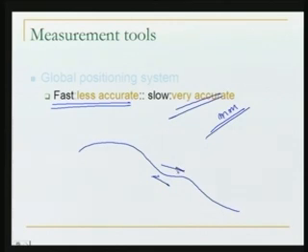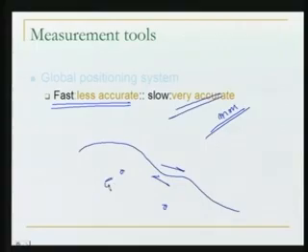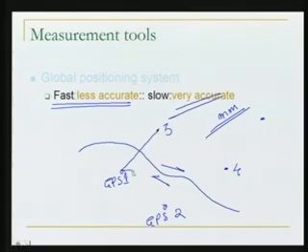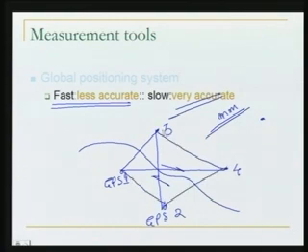So we need to monitor this fault. Is any movement taking place there? So what people are doing now, several researchers, they are putting GPS 1, GPS 2, similarly here also 3, 4 and so on. So we have a network of GPSs which are kept all along the fault line. So we have a network like this.